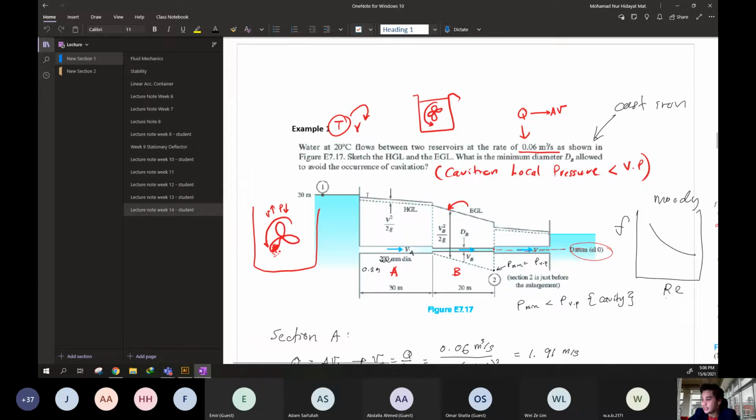So let's say 0.1 is the atmospheric pressure, but when we deal with cavitation, we must use the absolute measurement, because the quantity that indicates whether cavitation occurs depends on the absolute vapor pressure.